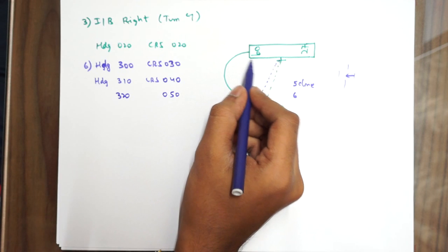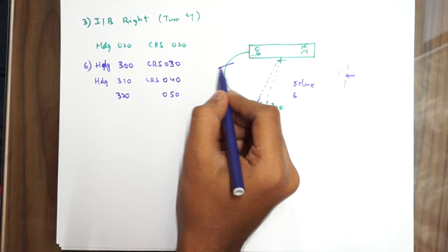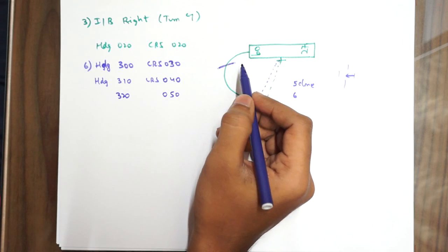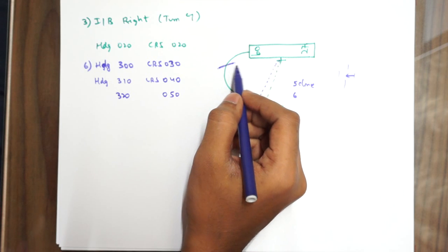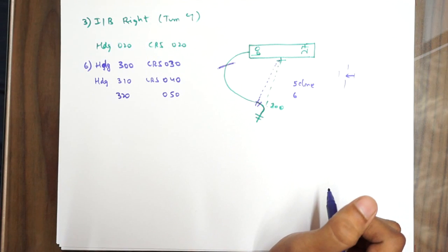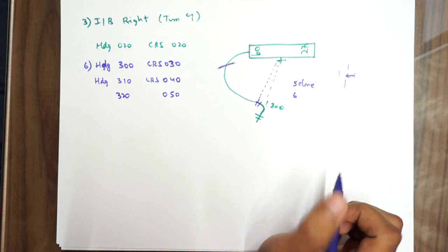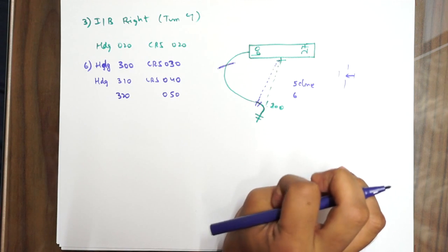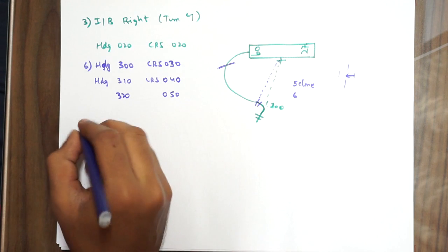050. So till you reach a lead radial somewhere here, whatever the lead radial is, it could be 080, or depending on whichever the lead radial is given on the chart, you will stop and then establish on a final approach track. Cool, sounds simple, right? The more you practice, you'll get hold of it.